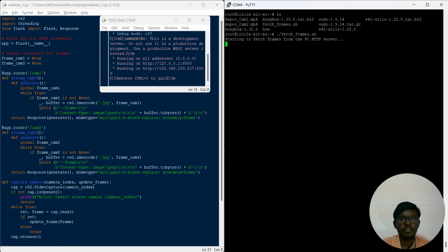So we moved on to other methods by hosting an HTTP server and transferring frames simultaneously at 1 frame per second. We tried this. So this was our Python setting in a separate Windows PC where we were running the HTTP server, which captured the video frames, stored them in a separate folder, and then transferred them to the Ubuntu kernel running in the PolarFire Icicle kit.